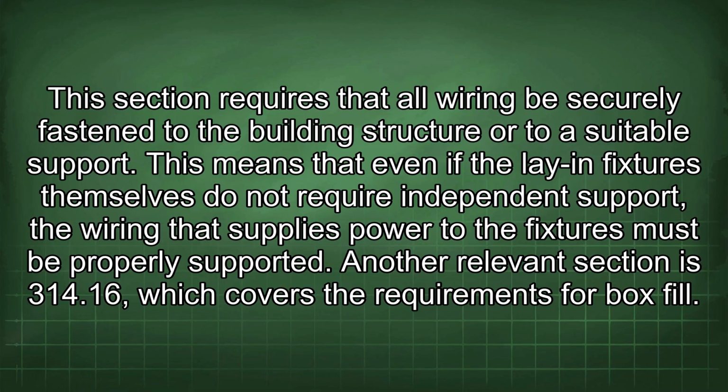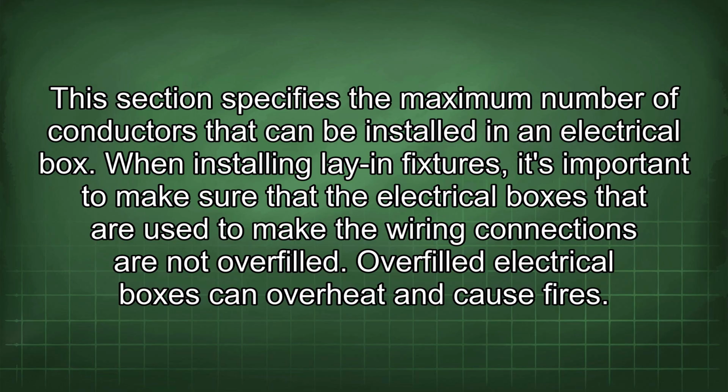Another relevant section is 314.16, which covers the requirements for box fill. This section specifies the maximum number of conductors that can be installed in an electrical box. When installing lay-in fixtures, it's important to make sure that the electrical boxes that are used to make the wiring connections are not overfilled. Overfilled electrical boxes can overheat and cause fires.